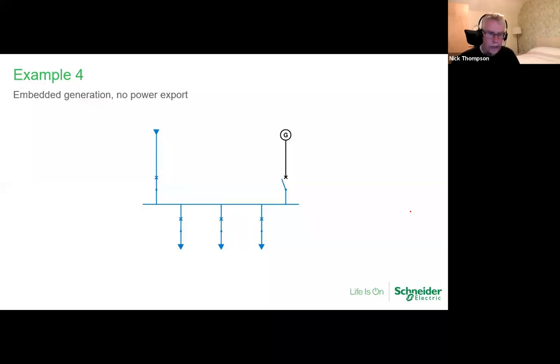That will then be taken out. That will prevent the circuit breaker from being closed manually, and then putting the key into the generator. It might be going to a key exchange box. Another way would be electrical interlocking, so that the protection relay would be blocked from closing the generator circuit breaker until the incoming supply circuit breaker has been tripped. And that's another way. Or it might be done via your SCADA or whatever